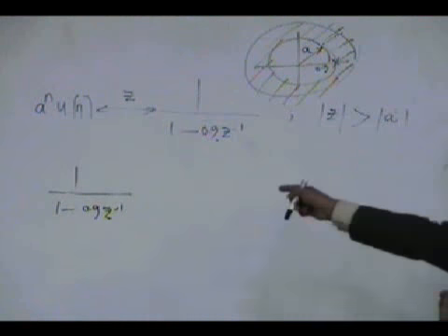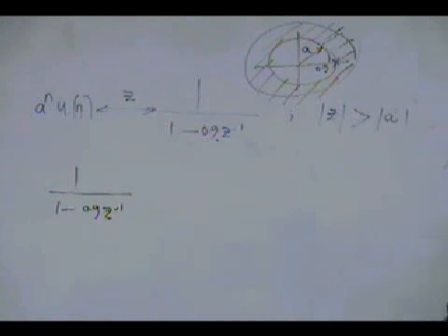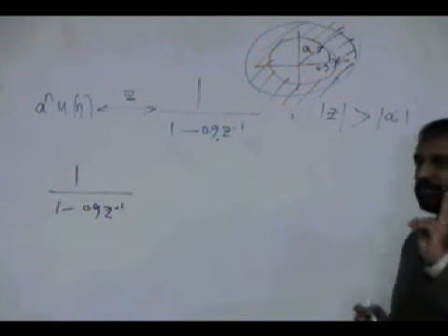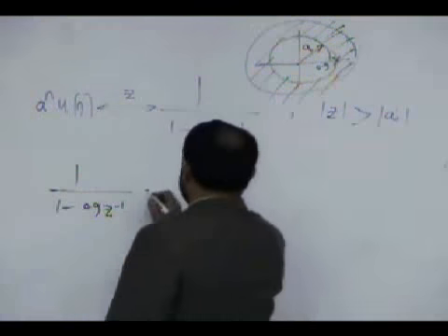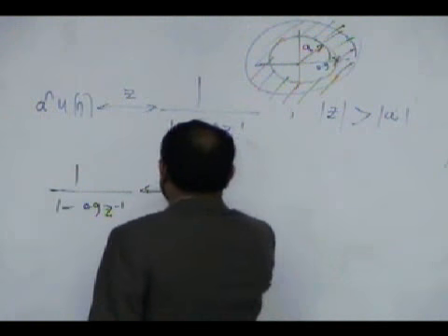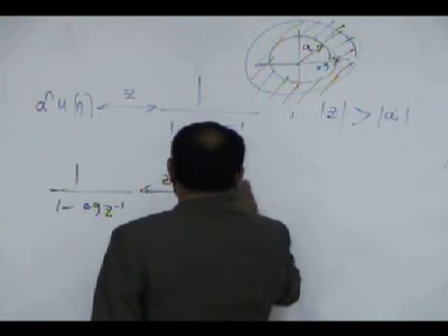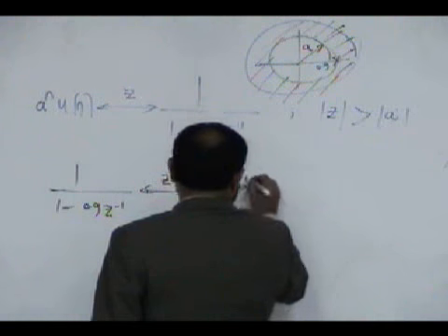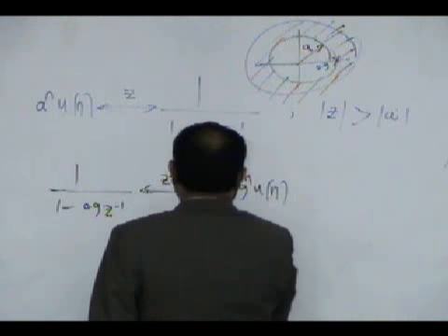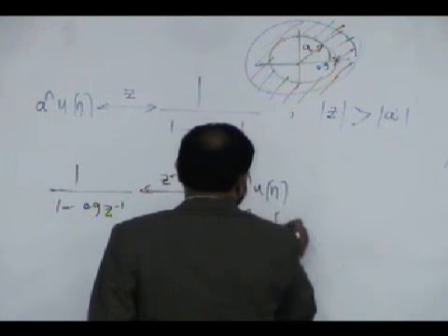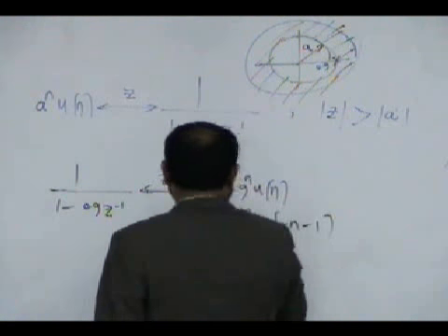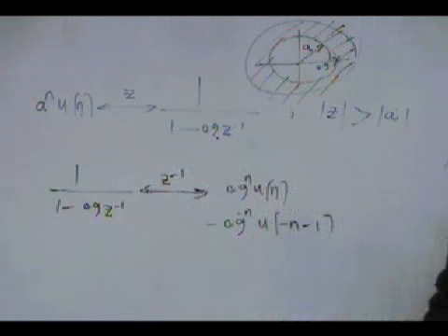One is that this Z transform is for a right hand side sequence, or for a left hand side sequence. So you always give two answers. This is important. You always give two answers. You say its inverse Z transform may be a^n, or in this case 0.9^n u[n], or minus 0.9^n u[-n-1]. So two options are there, and you mention both options.